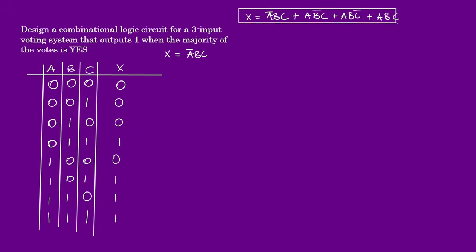So take note of these steps we're doing when solving Boolean combinational logic circuits. We first define the scope of the question, even before drawing a truth table, so we can get our heads around what's happening. Then we made our truth table. Then we had our expression. Now we're really going to get into the fun part, which is drawing the combinational logic circuits. The domain of this function includes A, B, and C. So we know we're going to have A and their negation, B and their negation, and so on.